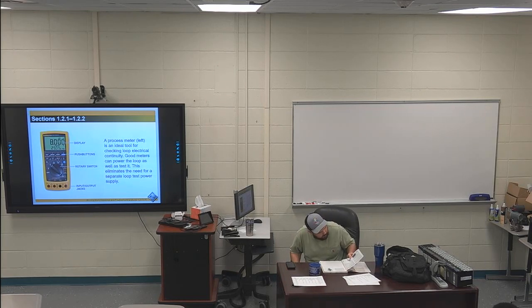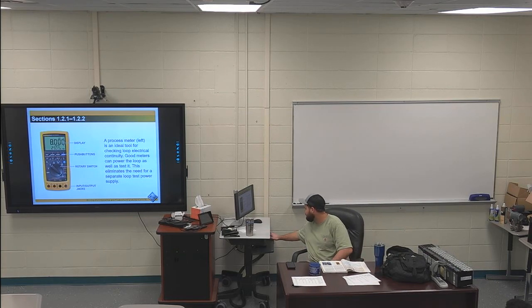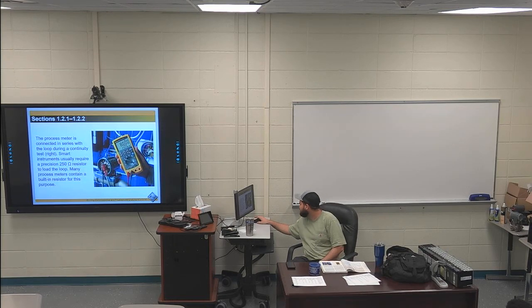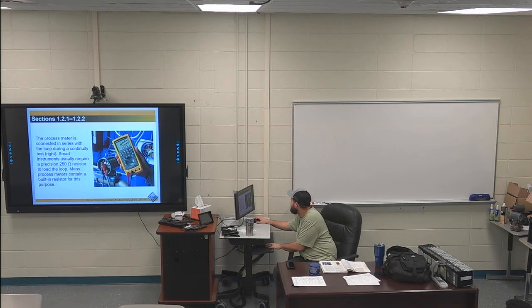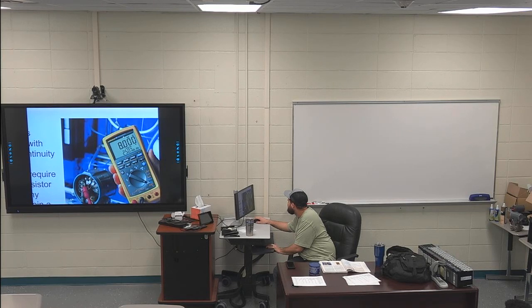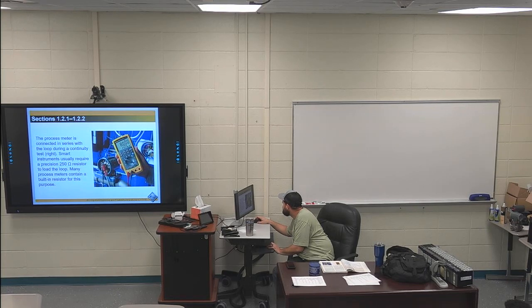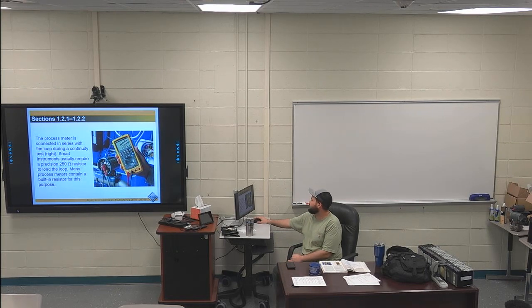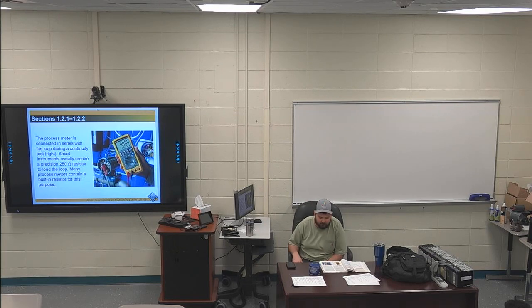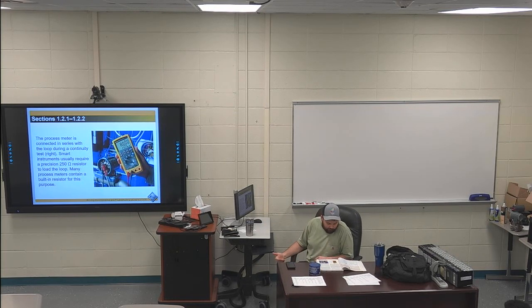Yep. In the simplified methods, this is with using just a digital multimeter. So you can go out there, and that's what I was talking about. That's what I've done out there, look for like a 4 to 20 milliamp signal. You can see in that picture, they're just testing to see. That still looks like a process meter. This is still a fancier meter than just a regular digital multimeter. But you can check with just a regular digital multimeter rather than having a process meter.